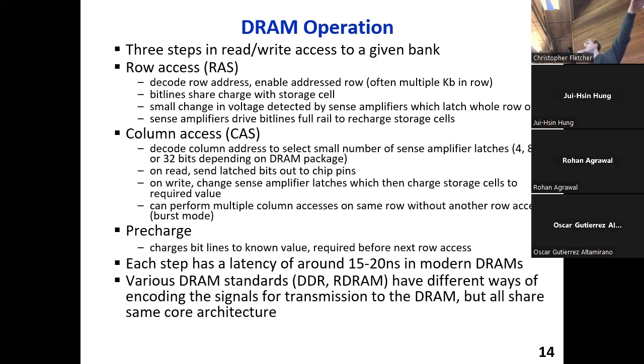So at the end of the row address strobe, we open a row of cells, we dump all of those cells onto the bit lines, and seamlessly in the background, that's where we slip the write back operation in. We're going to try to overlap this operation with the other stuff we have to do. The second thing, in a separate cycle, it's actually some amount of time later, we put the rest of the bits, which are responsible for picking which columns we're interested in, on the address lines, and that pulls out the subset of columns and pushes them to the chip pins.